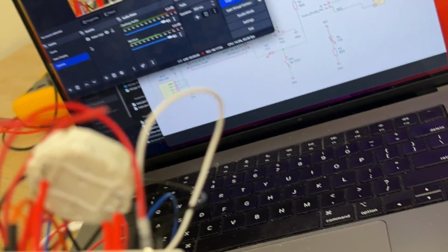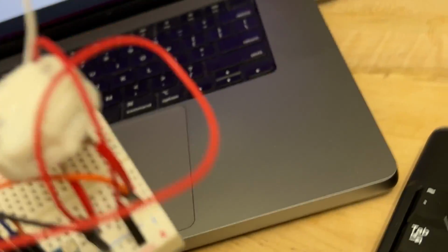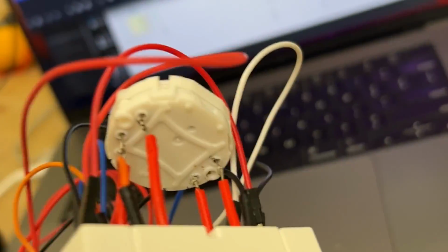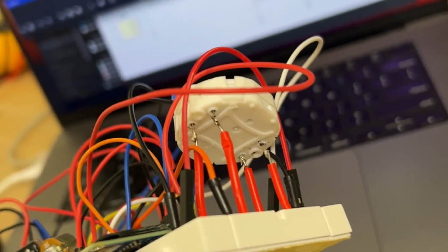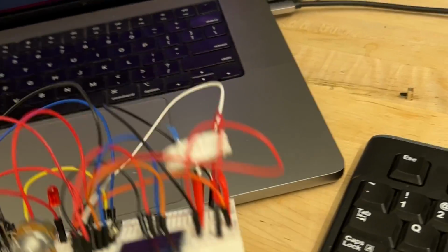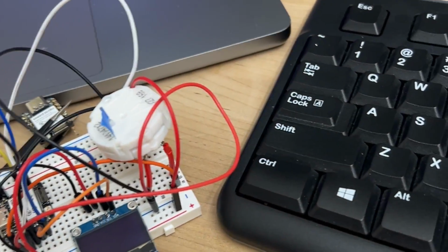The 2 coils are used for generating 2 magnetic fields in total, and it is using that to control which angle the motor should be turning to. Those 4 pins can be directly connected to your MCU analog output pins, so that you can use it to control the stepper motor's movements. All right.